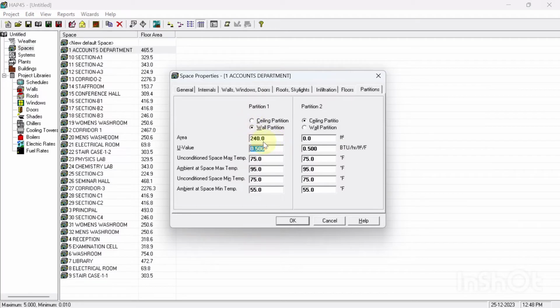And the U value for the wall partition, whatever. When you open the ASHRAE handbook, you will get that detail, 0.4. So here I have written it from the ASHRAE handbook. Now here also you have to change it, 107 and 102. Then here I am writing 60.